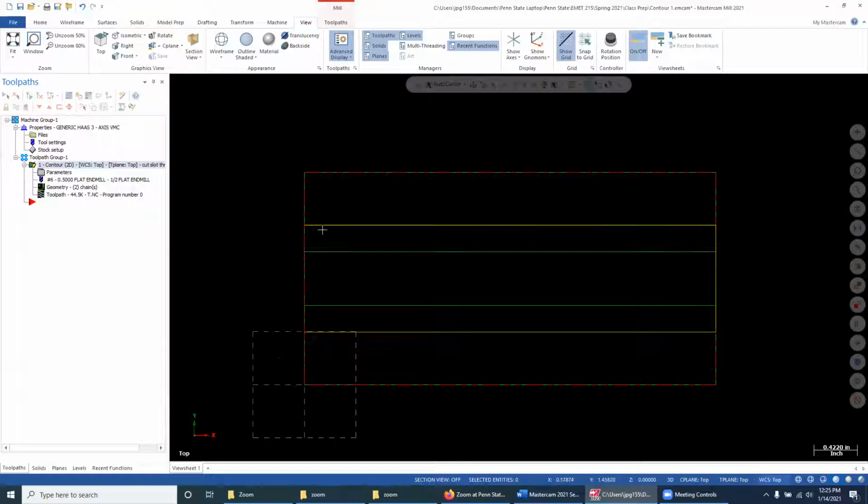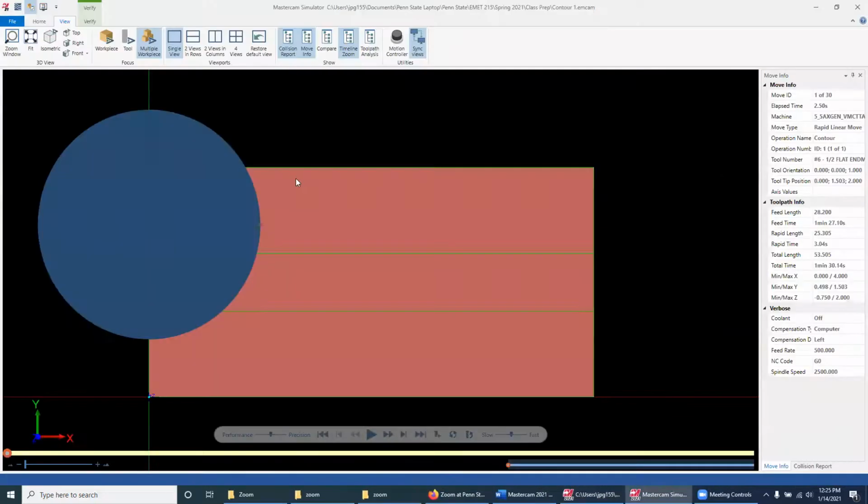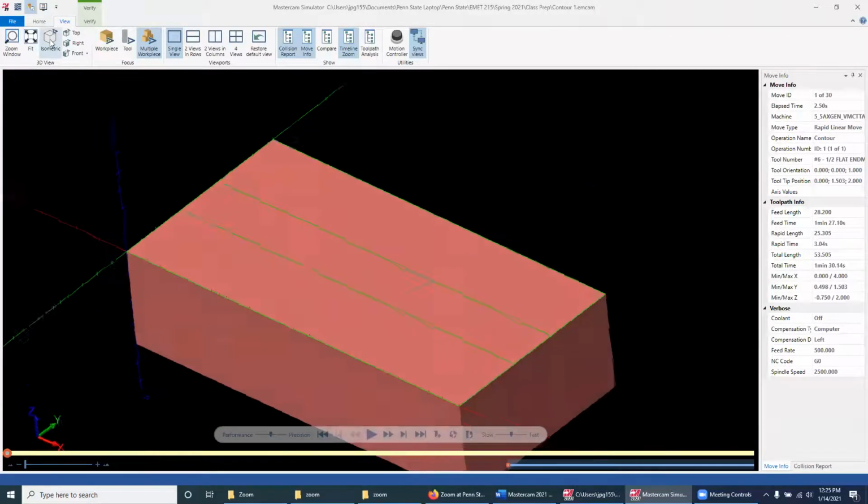And so now I've changed it to the left, which means it shifts this cutter radius out here to the left in this direction, but also out to the left in this direction. So now when I run my simulation, my part is going to look dramatically different simply because of the way that I've changed the cutter compensation to be.